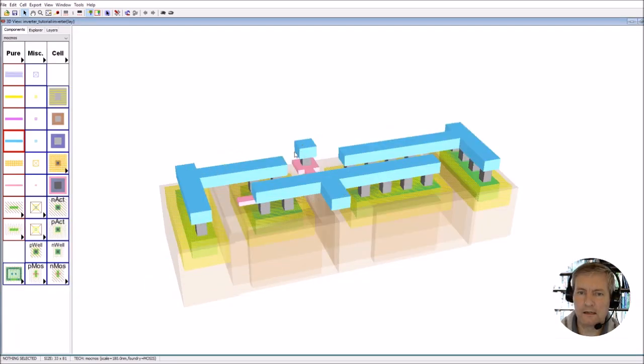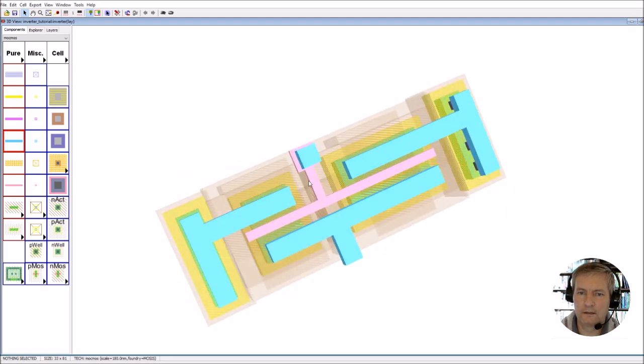So we've got the gate, so that's the gate over here, and you can see that the gate here runs across here, and the gate controls the current that's flowing. So the current's going to flow along the length of the transistor. So this is the width of the transistor here, and this is the length of the transistor. So in effect the channel becomes inverted or depleted as the channel here.